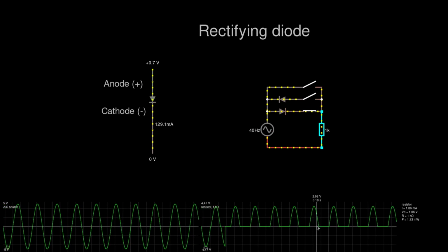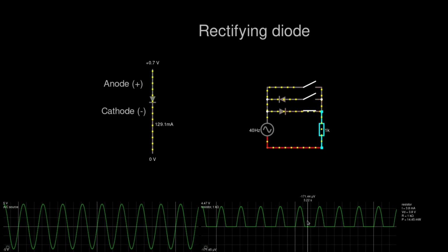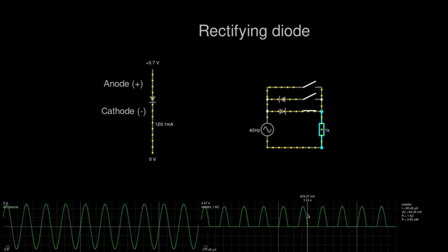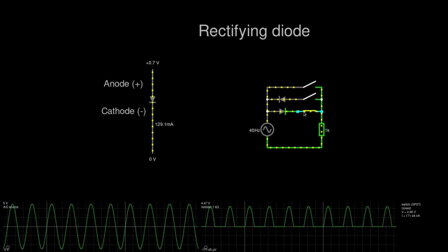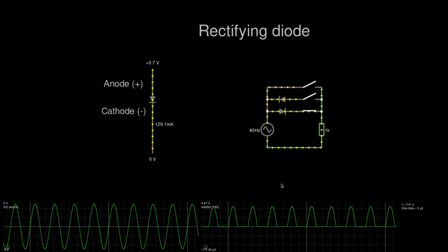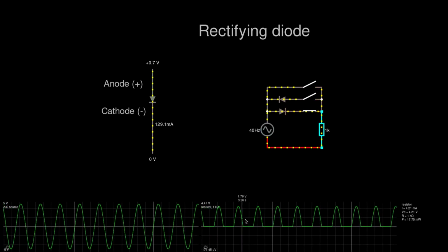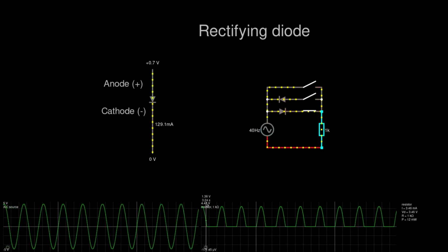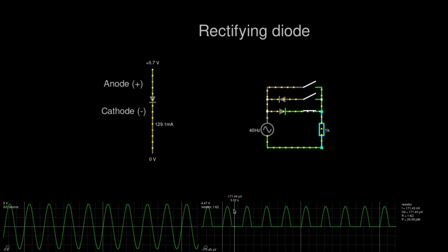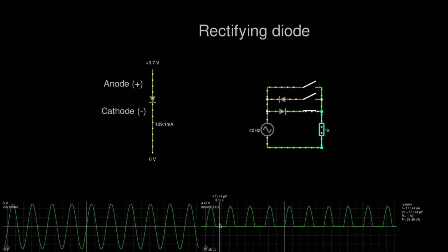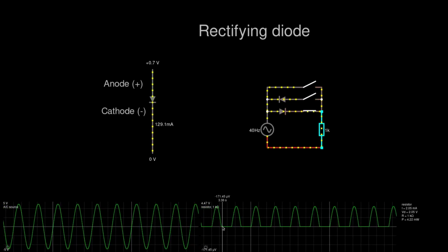So that is the rectification effect that the diode has. Basically, it's a valve. It lets the current go through it only one way and not the other. And now we've converted AC to DC with a bit of loss. On the positive side we've lost 0.5 volts and the whole negative side is lost. So basically we have only half the energy we had before rectification.